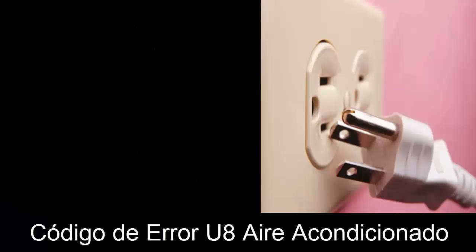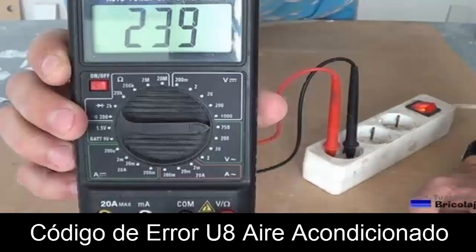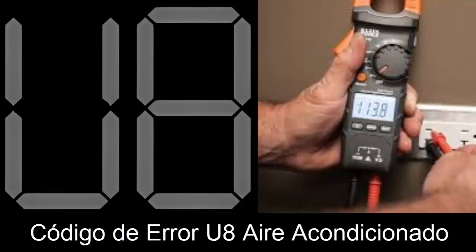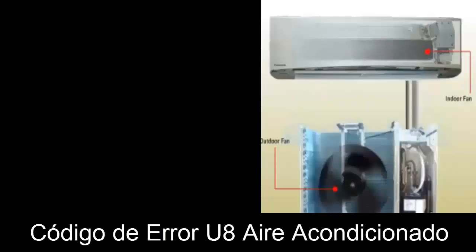1. As a first step, disconnect the equipment from the power source for several minutes, then reconnect it. This can reset the system and eliminate the error if it was caused by a temporary fault. 2. Ensure that the voltage supply from the external electrical grid is within the correct values. A value above or below 10% of the nominal voltage is considered acceptable. For example, for a 110 V supply, the problem may appear if the voltage drops below 100 volts.